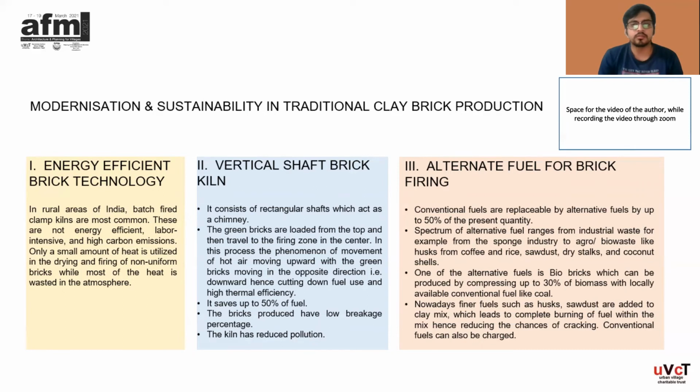And the third part, which is one of the most important techniques, is alternate fuel for brick firing. Conventional fuels are replaced by alternative fuels by up to 50% of the current quantity. The spectrum of alternative fuels ranges from industrial waste, for example from the sponge industry, to agro bio-waste like husks from coffee and rice, sawdust, dry stalks, and coconut shells.